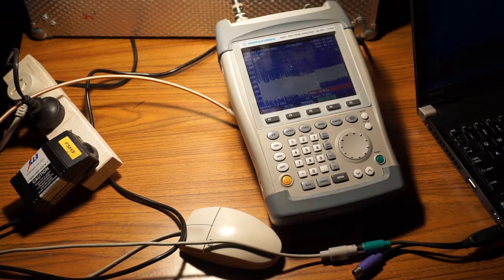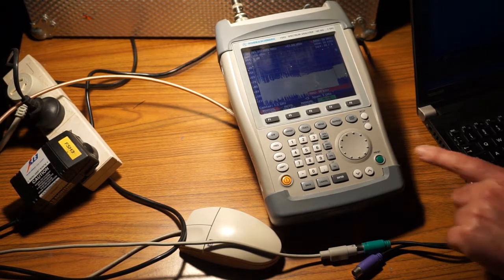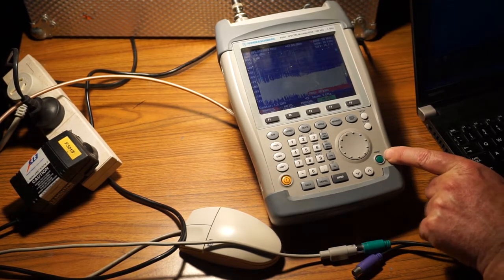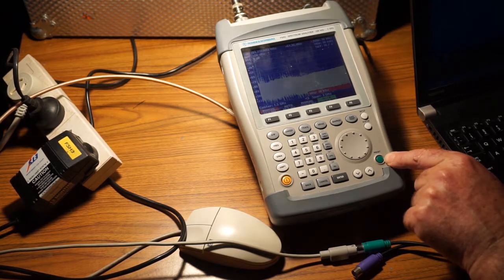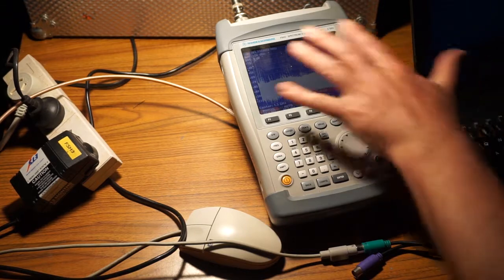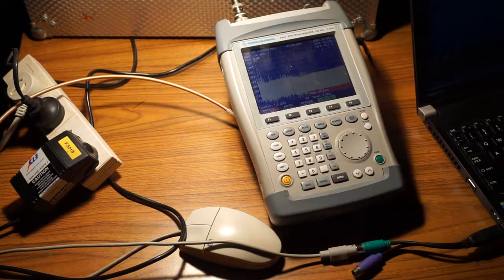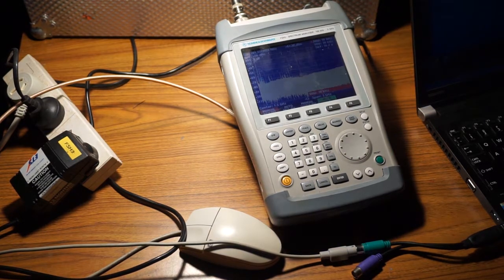So it does other tricks. If you want to save setups, we've got a preset here. If you press the preset, it just goes to factory preset conditions. But if you wanted to save all of the setup conditions, all those buttons the way I've got it set up now, you can save that. You've got multiple ones of those you can save, name and call back. If you're just doing, for instance, the same tests over and over again, it's sometimes useful to do that. So you could save your, let's say, scan the FM band. Yes.